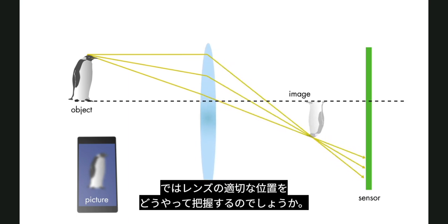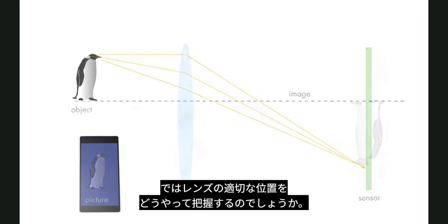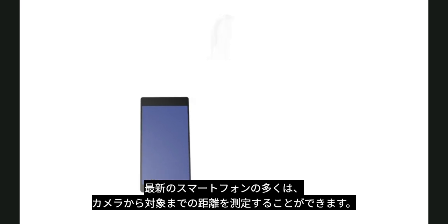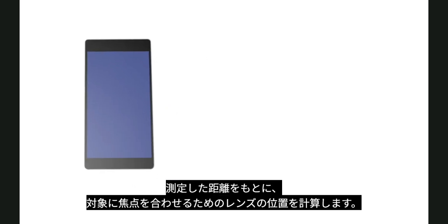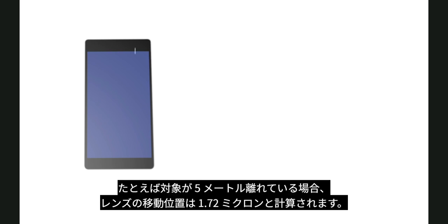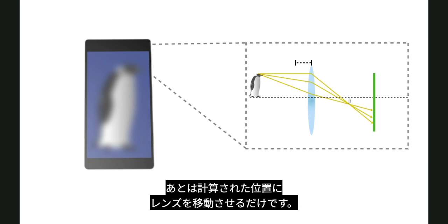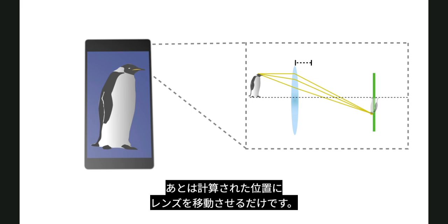But how do we know where the lens should be? Many modern smartphones are capable of measuring how far an object is from the phone camera. Based on that, the phone can do a quick calculation to tell us where the lens should go to get the object in focus. For example, if the object is 5 meters from us, the phone calculates that the lens should go to 1.72 microns. So all we need to do is move the lens to the position computed by the smartphone.